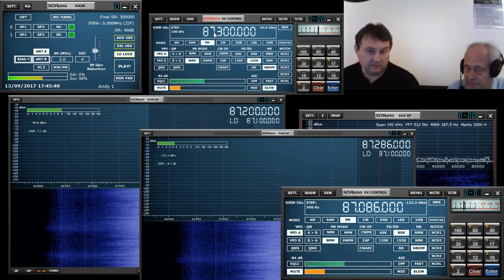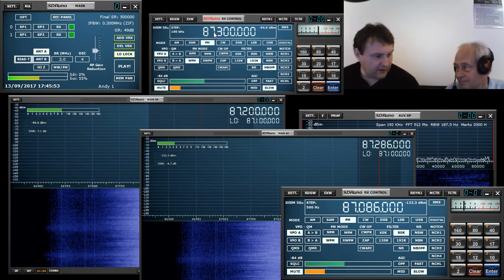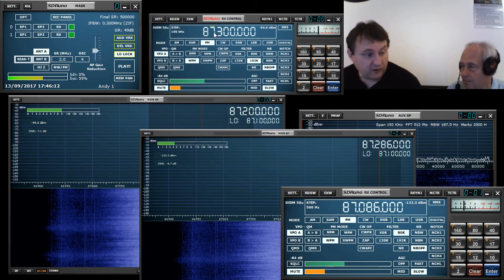Again, that information's on the data sheet, so you can see what the bands are. So if you're working around a band edge, then it's the LO frequency that's important for the filter selection, not what you're trying to demodulate, not your VFO frequency.